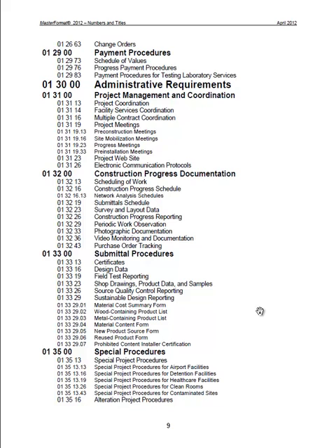We're getting into Division 1 here. This is all submittal procedures, how we want submittals on each particular item to come into the project. If you're a door and window supplier and you're supplying doors on a particular project, you need to supply shop drawings and information showing what you are supplying for doors so that they can be approved by the engineer.